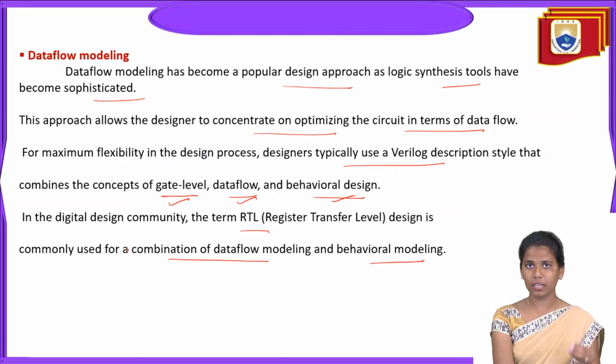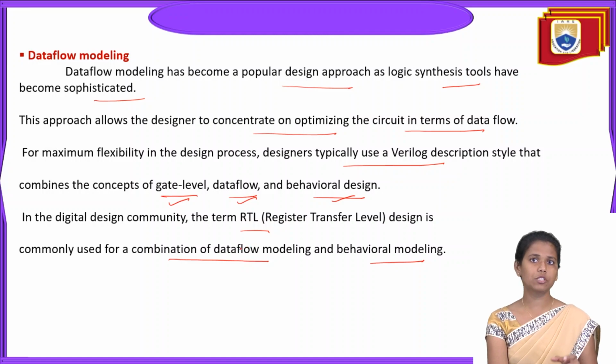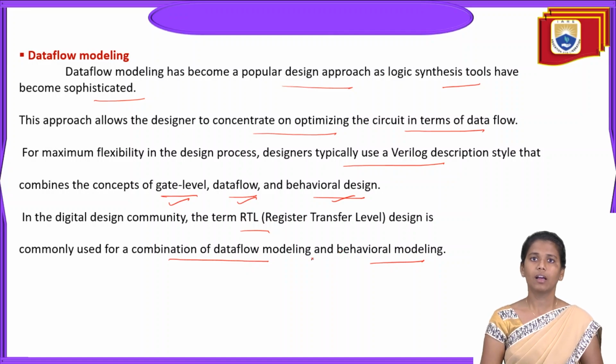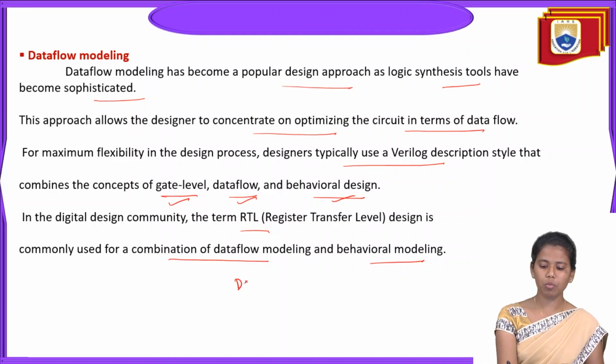So in the digital design community, we see this RTL based design. Some designs are concerned only with this RTL, that is register transfer level, and it is commonly used for the combination of data flow as well as behavioral modeling. So RTL is nothing but a combination of data flow modeling and behavioral modeling.